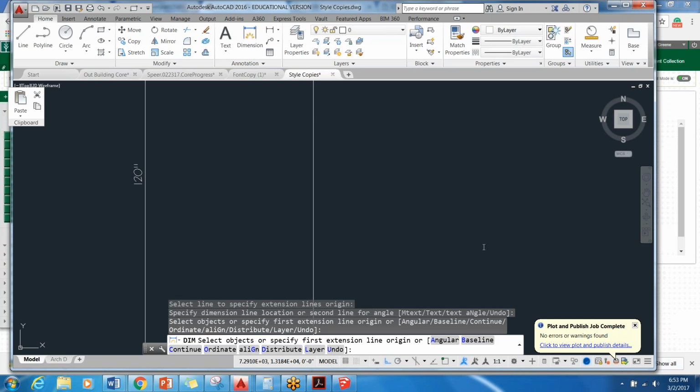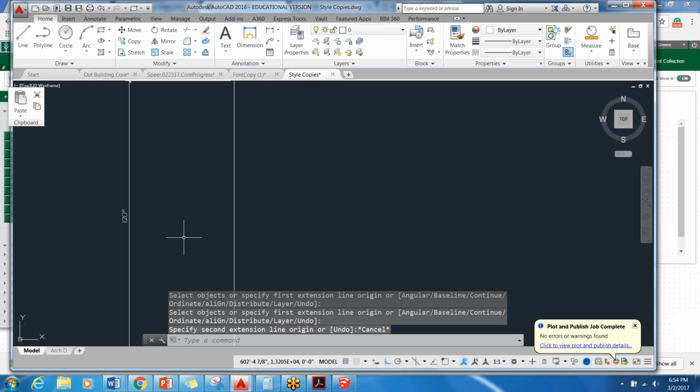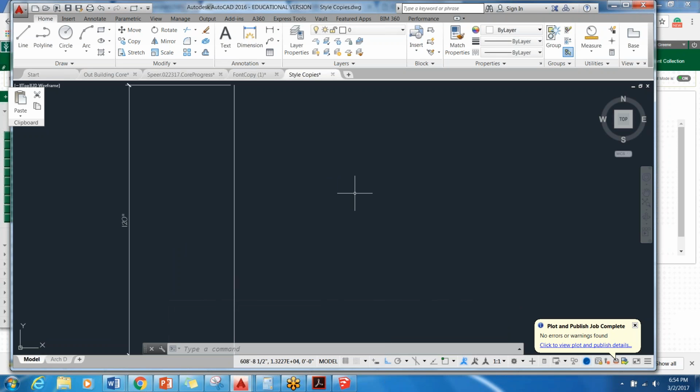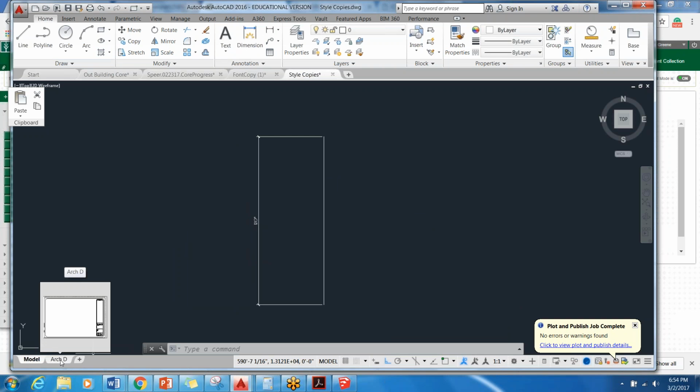It's either going to be as small as the drawing is on the screen or as big. But if you set it up annotatively, you can at least know in your layout size that it's going to print to whatever inch architectural ruler it says in the layout size. If you put something in here, then you have to know what size you're going to end up putting out on your layout. Does that make sense?